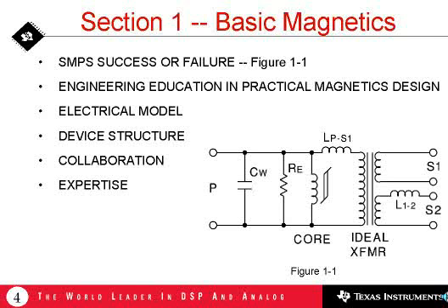Figure 1-1 shows the electrical equivalent circuit of what might be a forward converter power transformer, but this equivalent circuit shows all of the parasitics that are associated with that device. Normally we don't see those parasitics in the circuit diagram, but with a proper model of the circuit, including the parasitics, running this in a SPICE program, the effect of these parasitics on circuit performance can be determined.